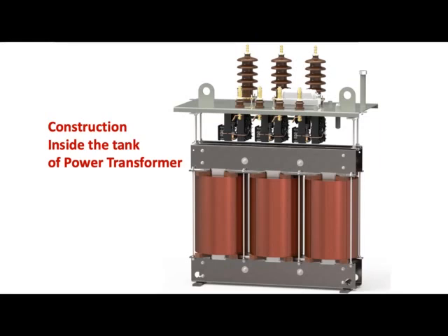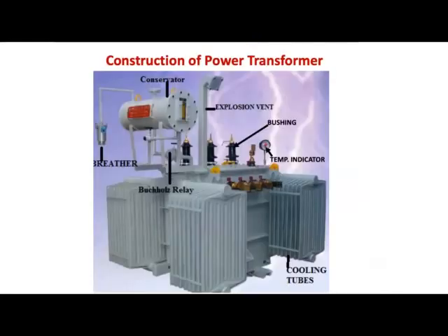Now this particular transformer or this type of transformer is placed in a tank for the actual power transformer or the distribution transformer. Inside this tank, you have got the transformer, and this tank is filled with oil for two purposes, cooling as well as the insulating purpose.